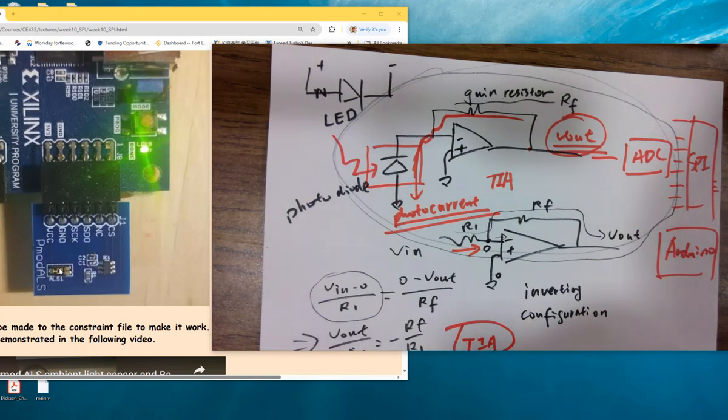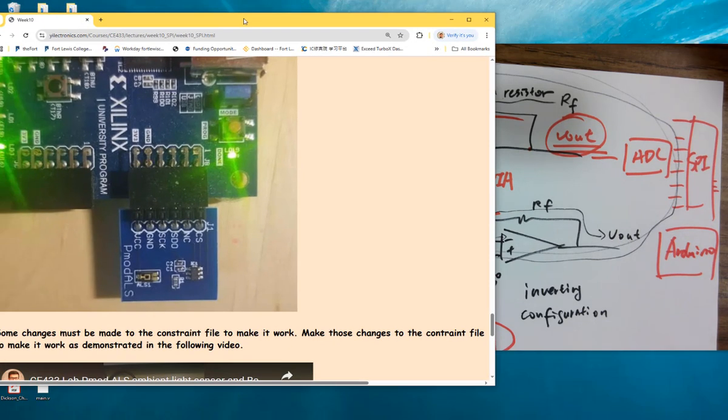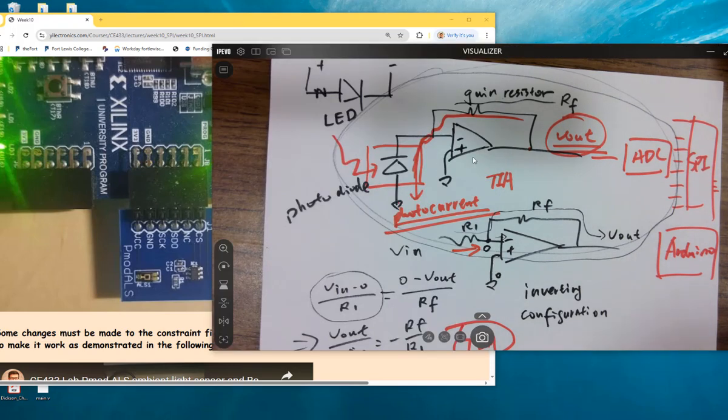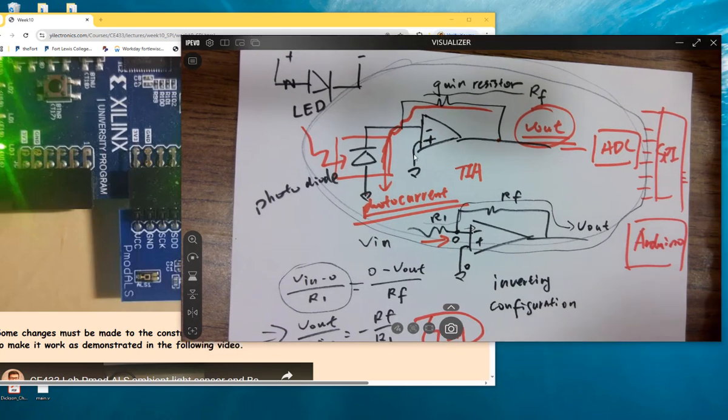So for our project, the goal is to design a digital sensor. It's one of the ideas. You can pick any analog signal. It could be temperature, could be light, could be a resistance, like a potentiometer, resistance output for some reason, okay? And since the FPGA has an ADC, eventually we will use that ADC as an ADC module. We may need a TIA or an amplifier to pre-amplify the analog signal, and that's a very important skill to learn, I think, for you guys.